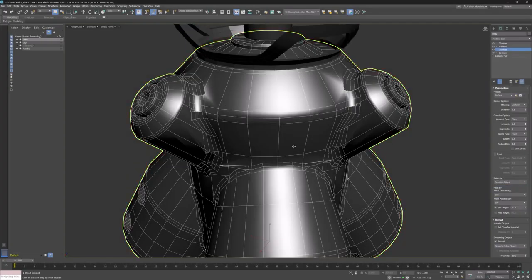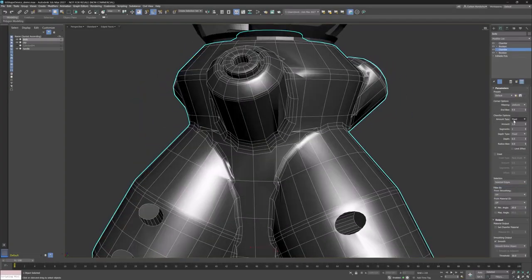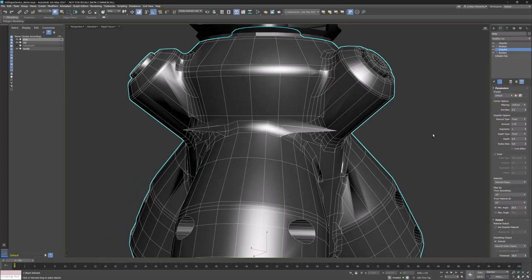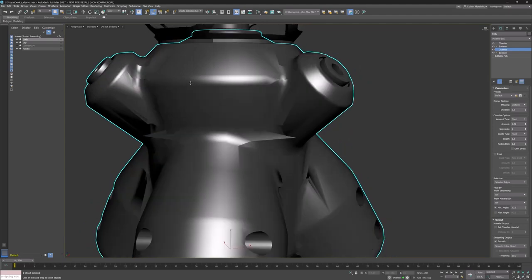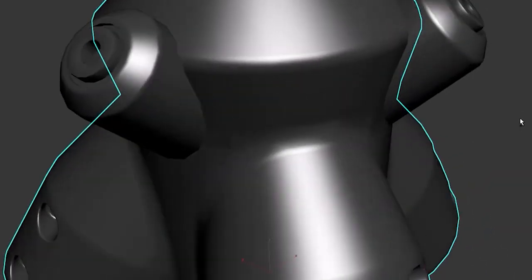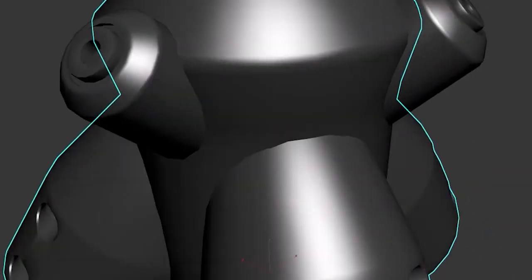Traditional chamfer depends heavily on the underlying topology. It offsets along existing edges, so when a Boolean creates uneven spacing or intersections, chamfer just follows that geometry, whether it's ideal or not. The tool is doing exactly what it was designed to do, but it can't give you the results you want if the topology isn't suited for it. That's the gap Smart Bevel is designed to fill.